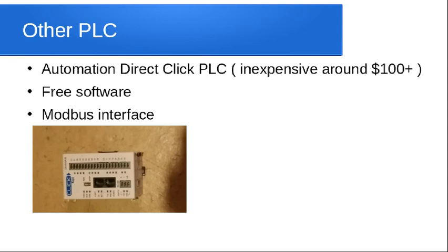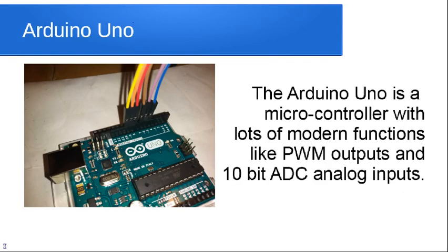Modbus is an open technology that you'll see and use later. That is what gives you your communications to the PLC, so that you're not locked into any specific driver or vendor. Gives you a whole open world, and you can really do some pretty impressive stuff there. The software is free, and that Modbus interface will pretty much let you see everything that the PLC sees.